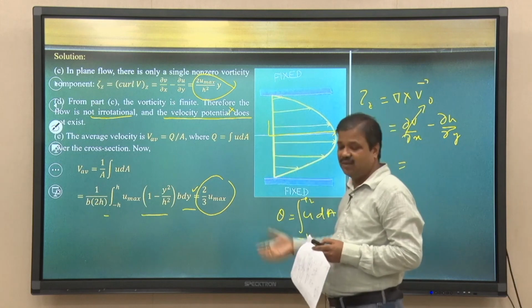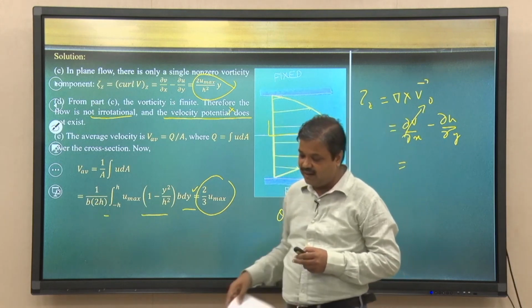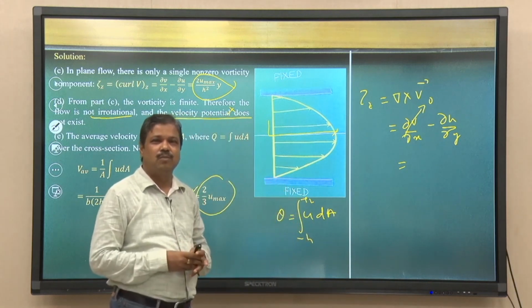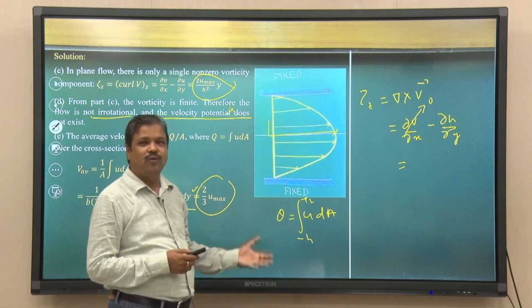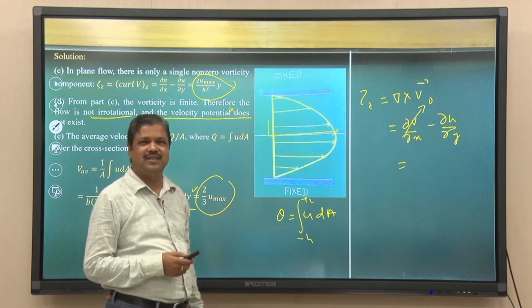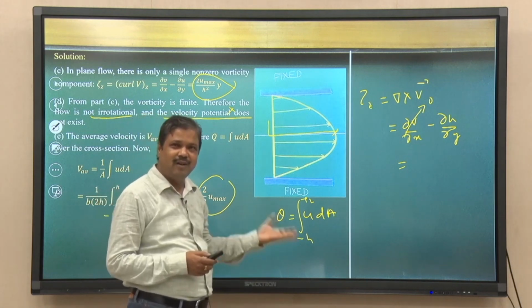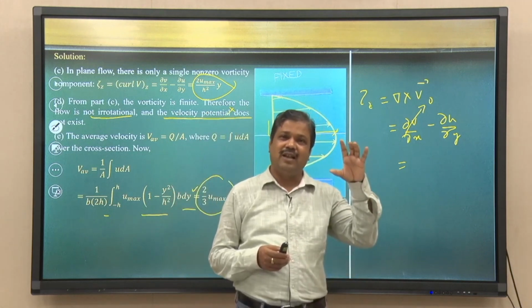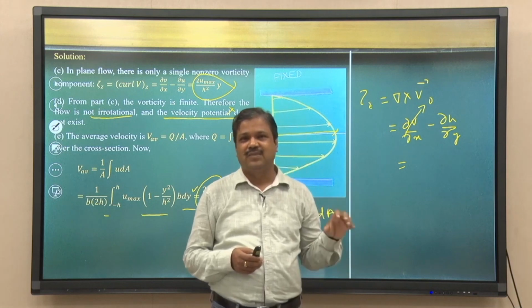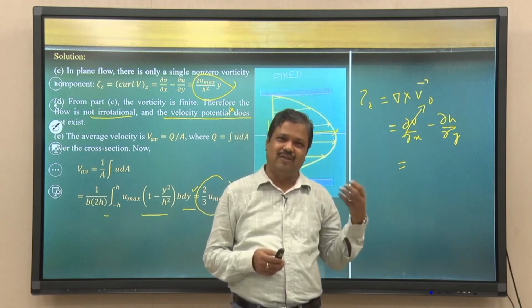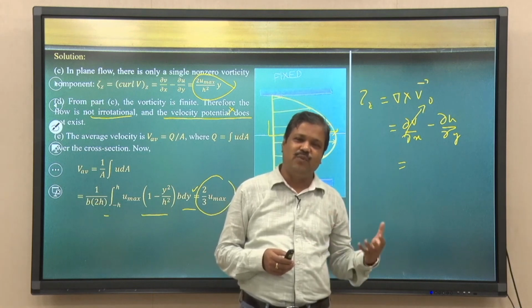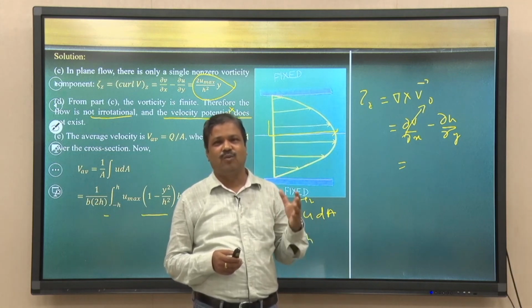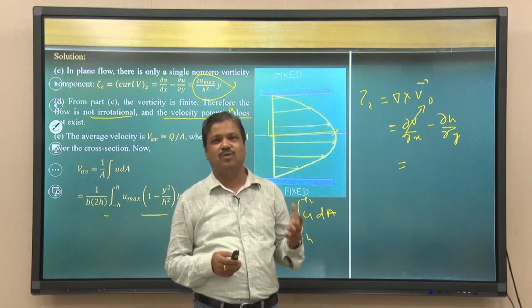So, that is an example here as compared to the integral approach, where we simplified many things. But in the differential approach, we need to do integrations and differentiations to get the pressure field, wall shear stress, stream functions, velocity potential function, with a lot of series of approximations. Two-dimensional flow, incompressible, Newtonian fluid. So, I am repeating it to tell you that fluid flow problems are not easy. You simplify for specific cases to get some solutions.